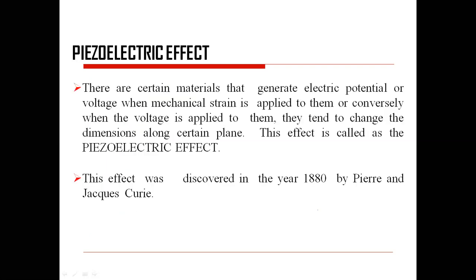The first one which we are considering is the piezoelectric effect, and this can be used as a transducer as well as an inverse transducer. Now, how can this be used as a transducer or inverse transducer? Because when we apply a force on this particular transducer, a voltage in proportion to the applied force will be generated, and vice versa.